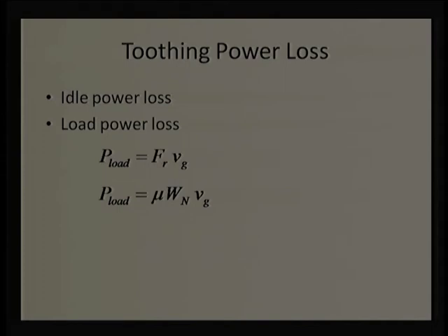As the load has such high variation at the point of contact, naturally mu is going to vary continuously. Talking about Wn, again the point of contact, or line of contact, is continuously changing. Naturally, this Wn will not remain fixed, it is also going to change. So, mu is going to change, Wn is going to change, and Vg is also going to change.